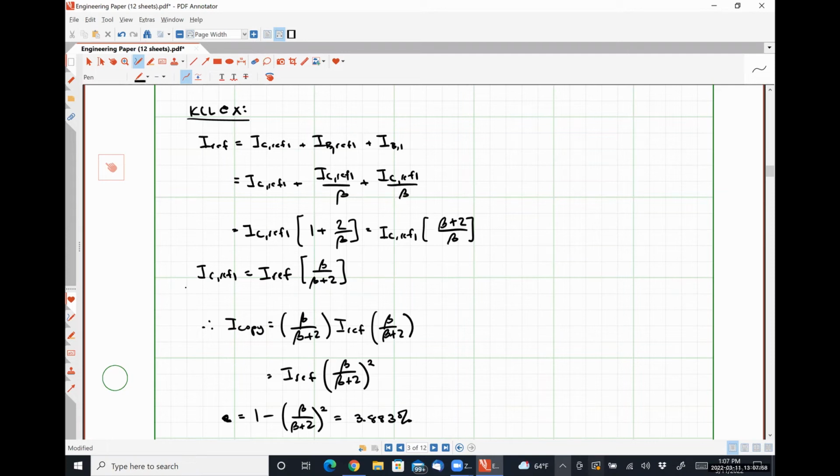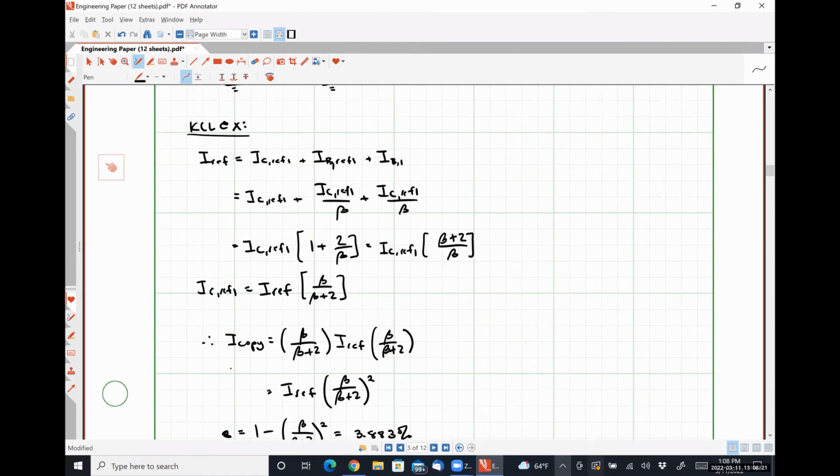I see confusion on your face. Why is there confusion? No. So the reason why I say the error isn't more is because we're only copying it twice, okay? So in the previous example, or the first example that we worked, we had roughly a 5% error. And the reason for that is because the copies that we were making were made up of multiple transistors, right? But these are just single transistors everywhere. So the error is not as bad because we're not copying it as many times.